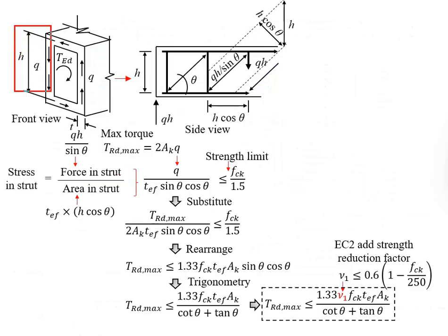By referring to the diagram here, you know that the effective height here is calculated on the basis of the central axis of the effective thickness. You're going to bring this height here. And then the shear force will be the shear flow times the effective height.